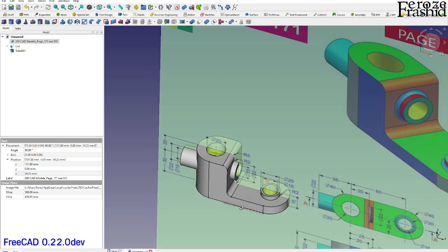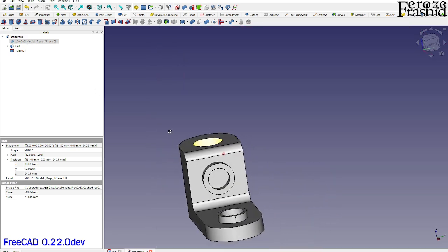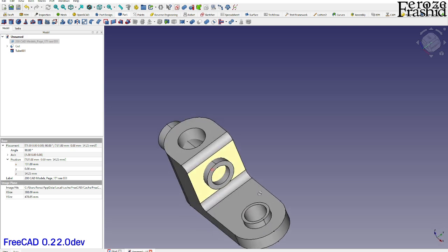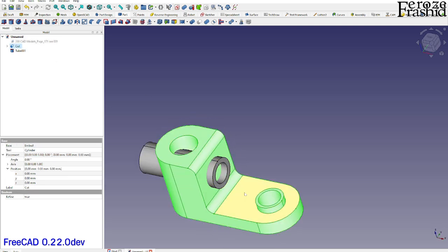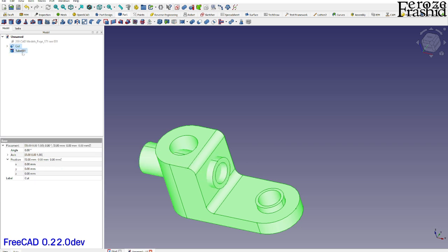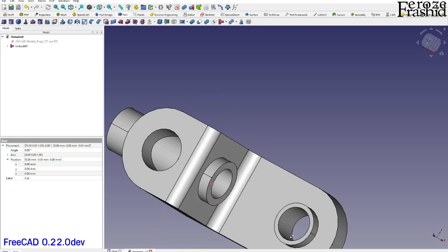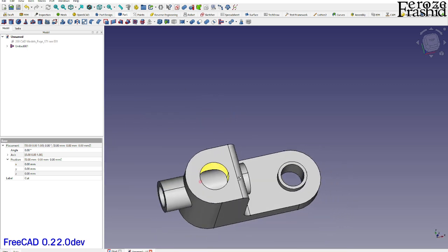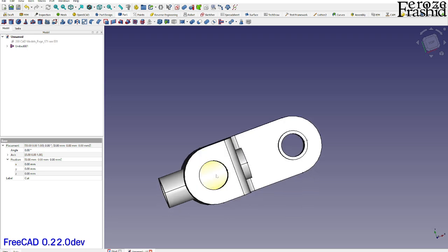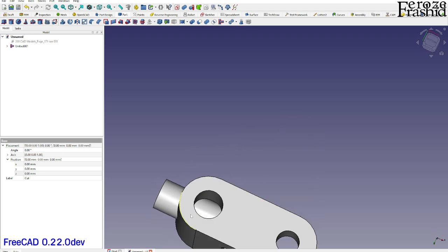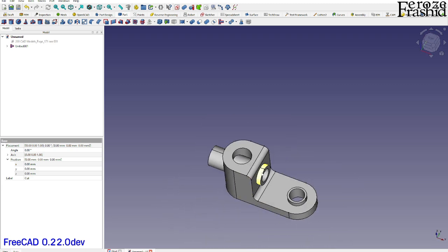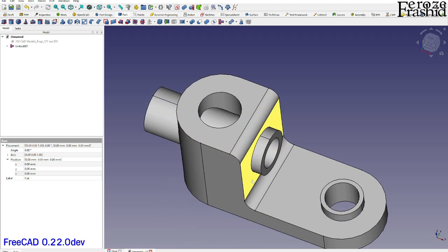Right. So now we want to make a hole through here. We can take the cut, this main object, and take the tube as the second choice and come here, say embed object. When we do the embedding, it makes that through hole just like it did here, but now it's blocking this through hole, that vertical hole right here. This is what I was trying to say previously. We should be careful on this part, which hole to make first.